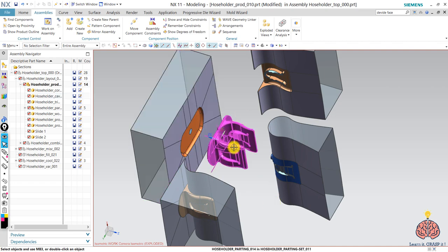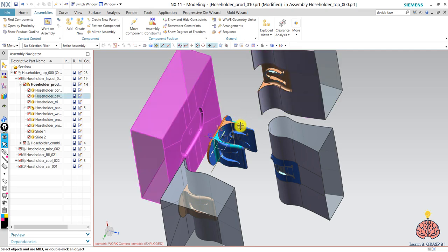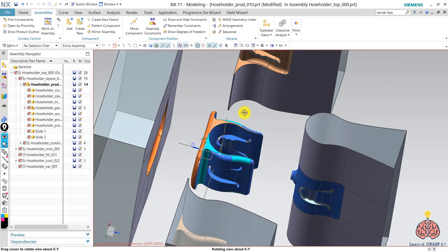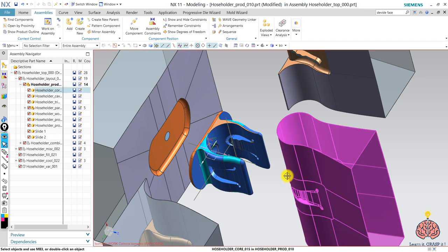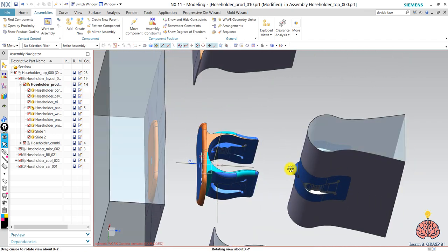Will start injecting in plastic. After the cooling, the core will get out, and the part will spring back to its original shape, and the slides will go out, and of course injection is going to happen from the core, and then you get your desired products right here.